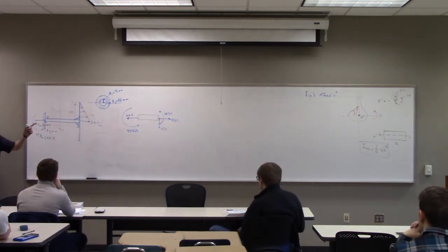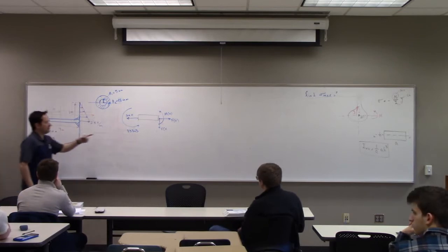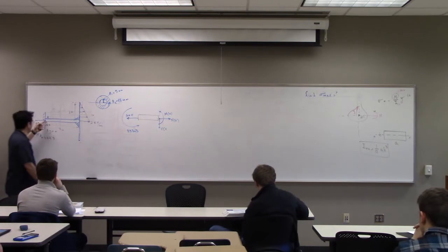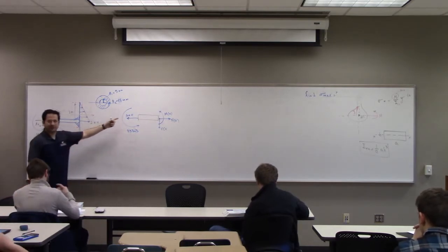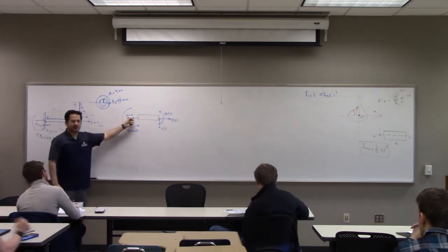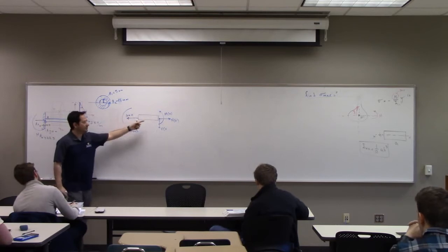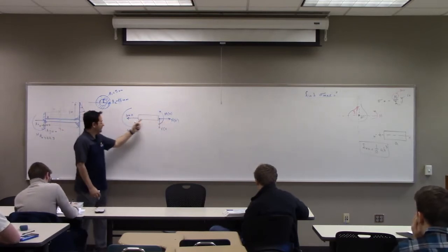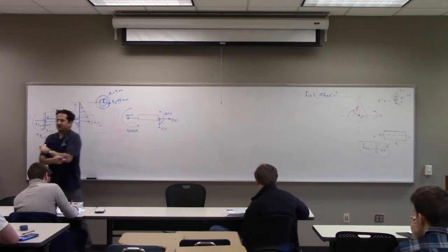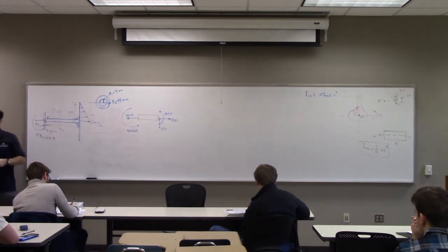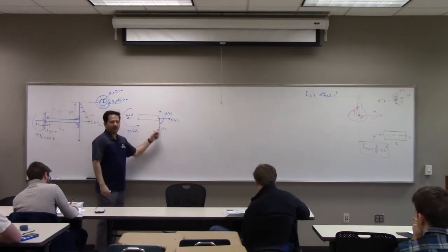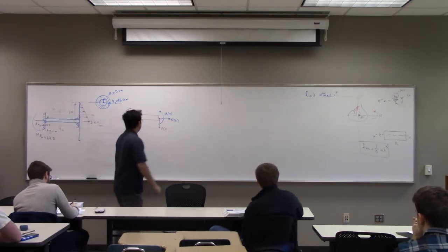Always think about those things. Usually we do only MX, but in this case we actually do have axial load. Don't forget that. So you should consider NX in analysis too. Don't eliminate it. But if you don't have any axial load effect, don't waste your time with NX, just put 0 there. But here you do have something, so you put NX, VX, and MX.